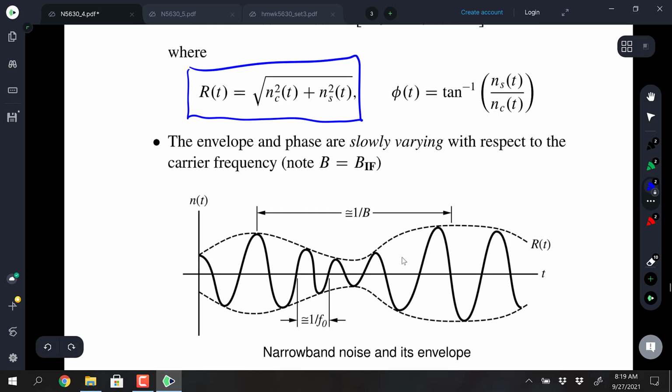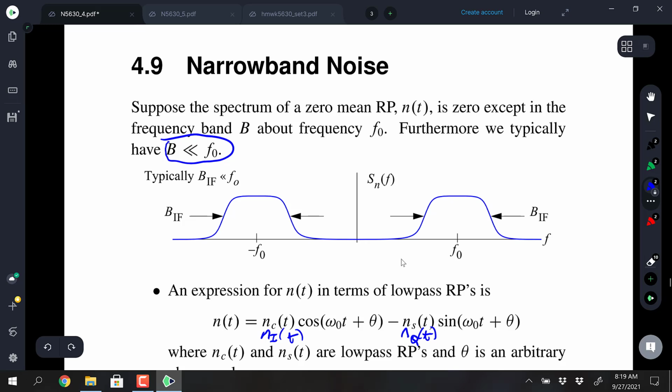I'm pretty sure, though, I'm just going to step right out and say I think that it'll be N naught over 2, but then when we appropriately scale it by the noise equivalent bandwidth, we're going to get N over 2. And then the combination of the powers at the negative frequency and the positive frequency will be N, and that's the variance.